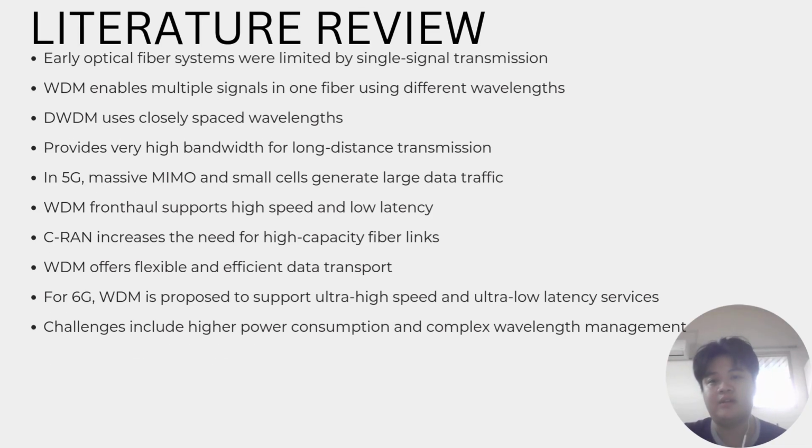Next will be the literature review. Early optical fiber systems were limited to transmitting only a single signal per fiber, which restricted capacity. WDM was introduced to overcome this limitation by allowing multiple signals to travel in the same fiber using different wavelengths. Dense WDM, or DWDM, uses closely spaced wavelengths and provides very high bandwidth over long-distance transmission.